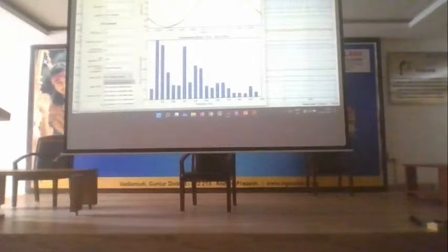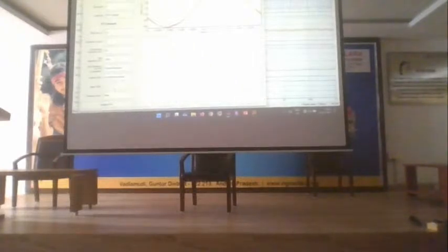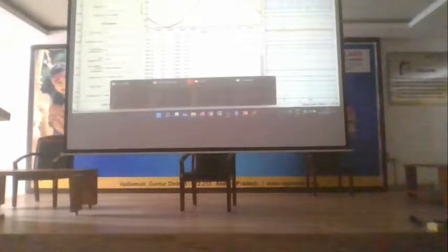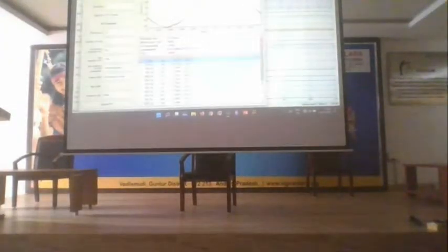And also if you want you can see the list. See that the DC offset current, this is one of the requirements. We are only at 0.2 percent. There you go. So at different frequency components, none of the harmonics is greater than 3%.